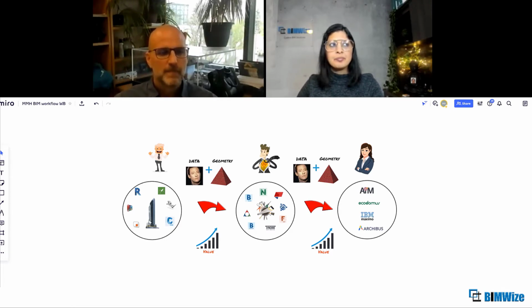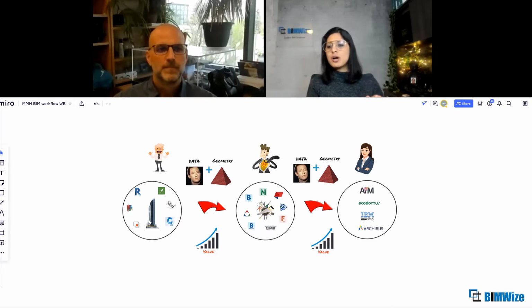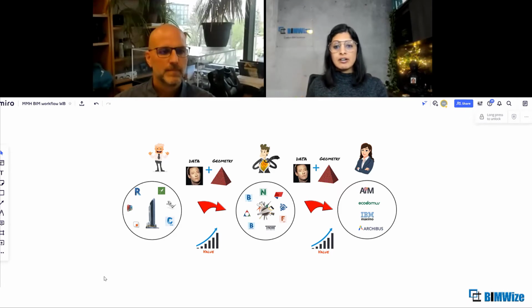Okay, I get it. And I think it's very commonly agreed in the industry that BIM is data plus geometry. LOD is supposed to define the geometrical modeling that we do. But does LOD also define the data modeling we need to do? Does it even define that? Let's say I have a model and an element in that model is not geometrically well developed, but it has a whole set of parameters that has information that is required. Do you think it would suffice to a certain level of LOD?